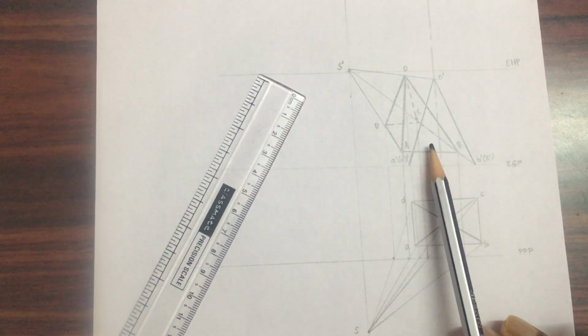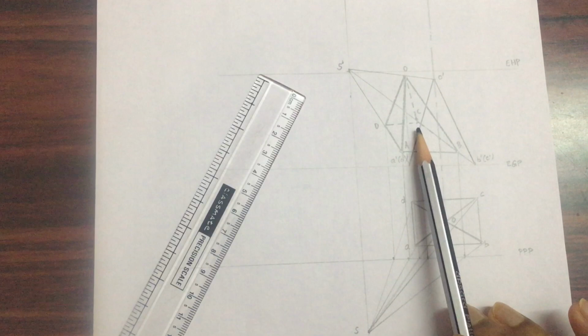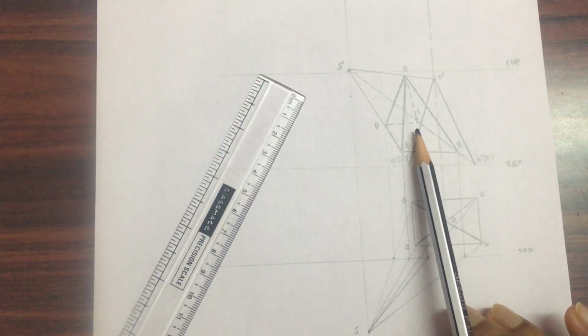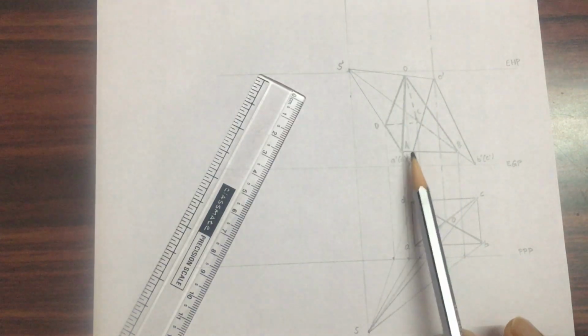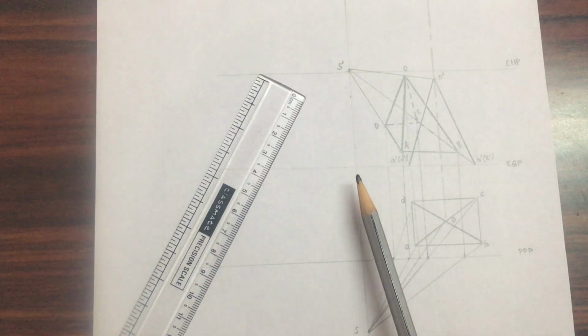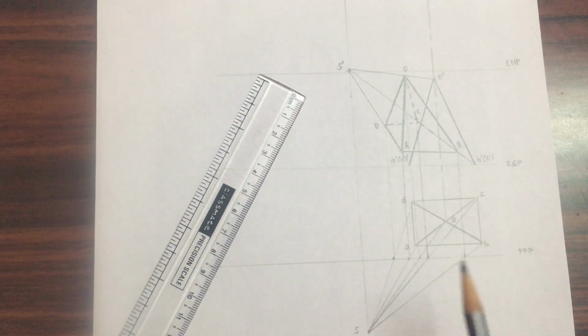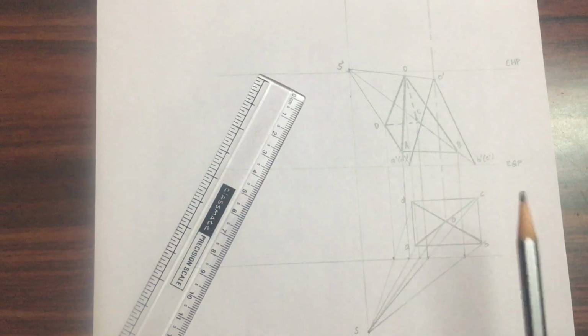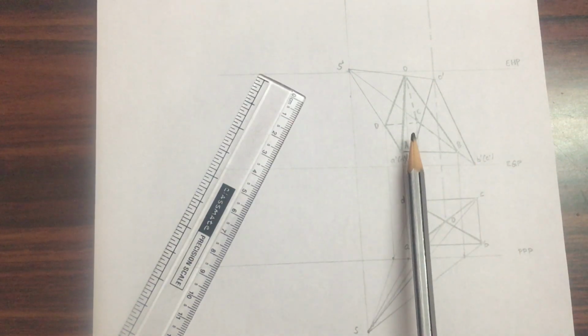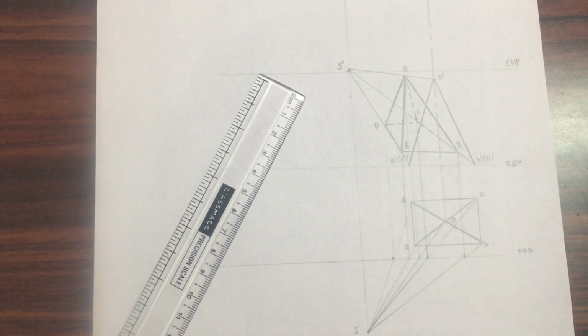Of these 8 edges, there are 3 edges which are to be drawn using dotted lines. If you are drawing them as dotted lines, ensure that you draw them as darker dotted lines. Everything other than this particular view is to be drawn as lighter lines. All other lines, that includes the top view, the front view, and all other lines in this problem. Okay, so only this is to be drawn using darker lines.